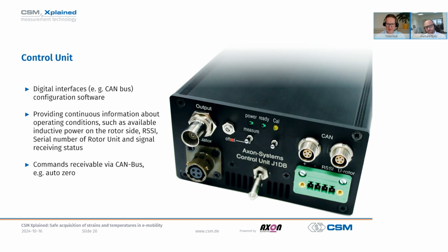Exactly. Just imagine you have a big measurement chain with hundreds of measuring points on your CAN bus and a lot of systems in between. And finally, on your monitor, you miss a signal, and then it's very difficult to see where it is coming from. Then it's really helpful, and it will remain a promise in future systems too, that you have the possibility to just use a multimeter or oscilloscope and look at the original data at the system. So this is really helpful and makes it easy to use. Yeah, it sounds very practical for the practical guys out there.